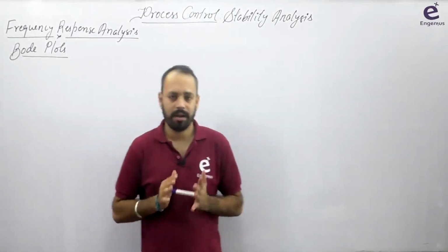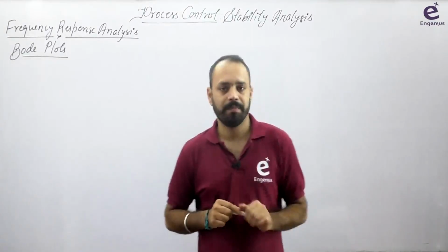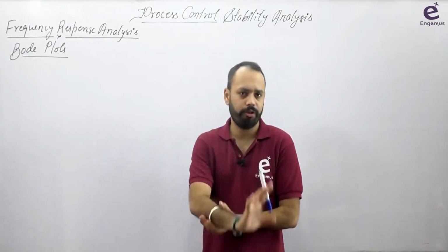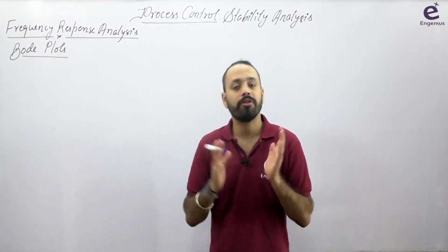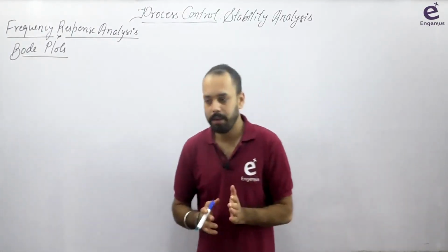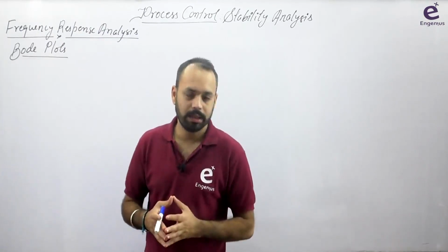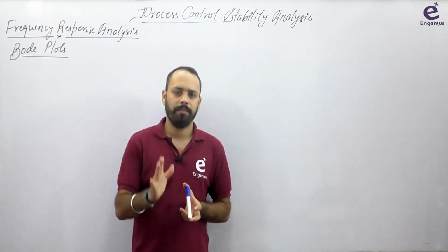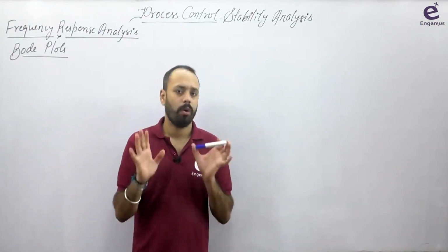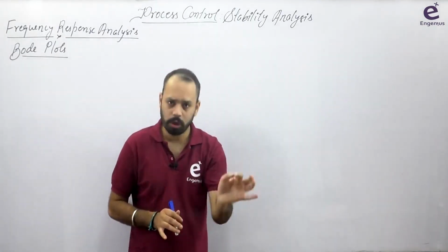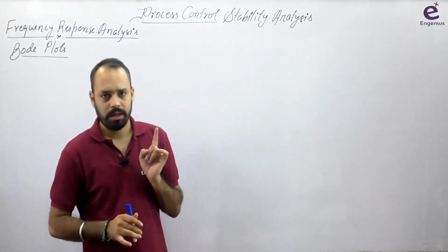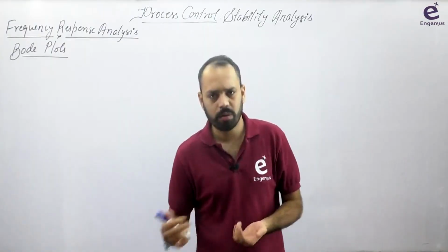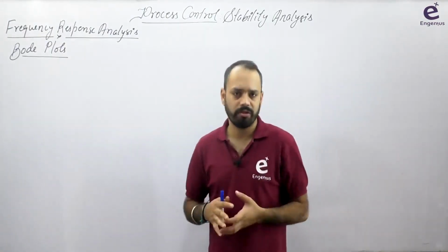In the last lecture, I discussed the amplitude ratio and phi of individual components, and I told you how you can find the AR and phi of a transfer function which you can make by multiplying the individual transfer functions, right? So what you have to do is make a table. On that table, mention all those 7 basic components, because once you know the AR and phi of those basic components, then you can always calculate the AR and phi of the overall transfer function.